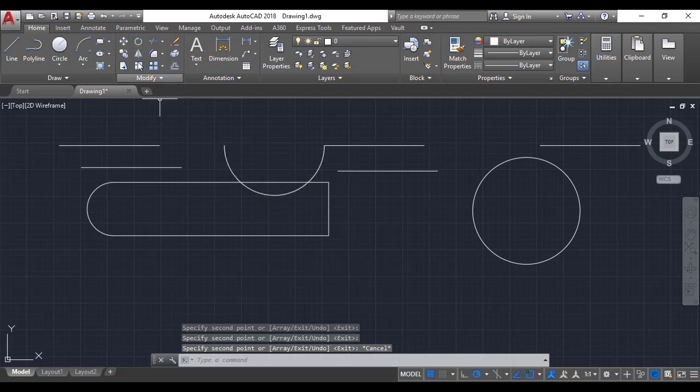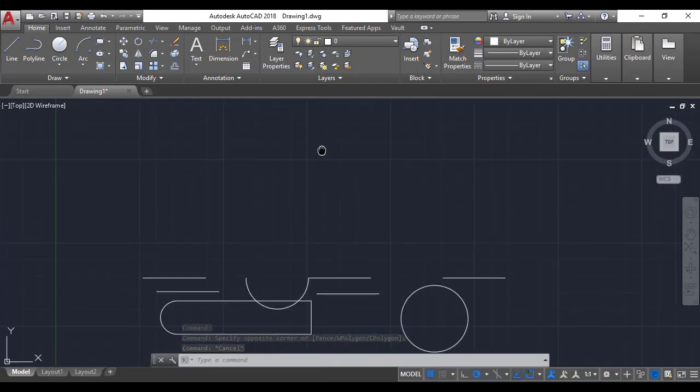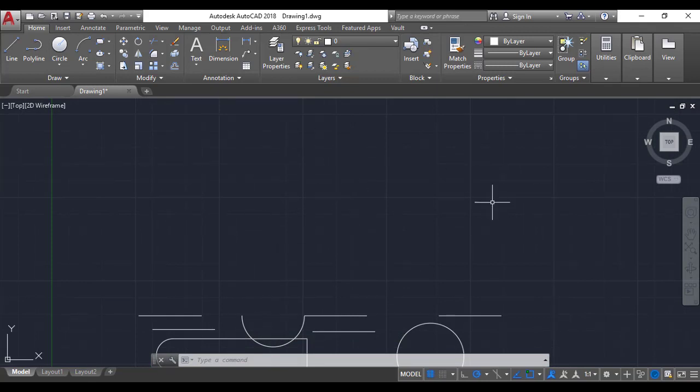Alright, we've also got a mirror command. I know that you get these office cubicles that you maybe have on the one side and you want to copy over the extent of the wall, then you can use the mirror tool to do that. So let's say we create a line in the middle and we create maybe a circle on this side, and you want that circle at the same distance across on the other side of this line.